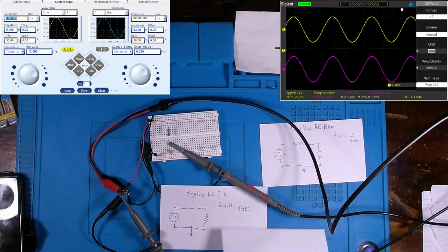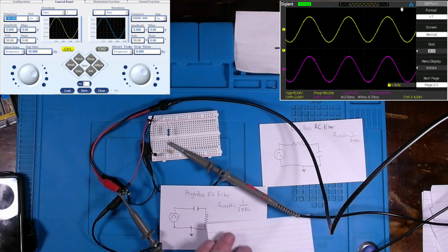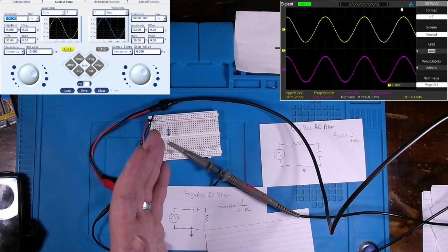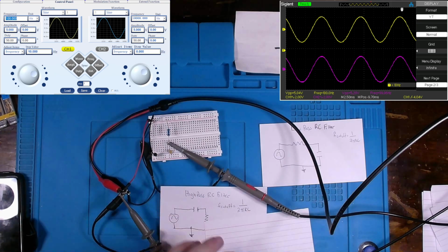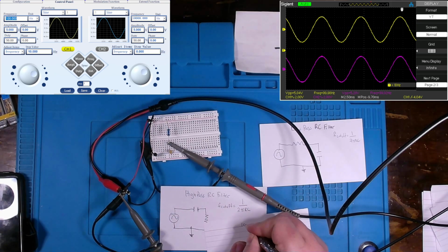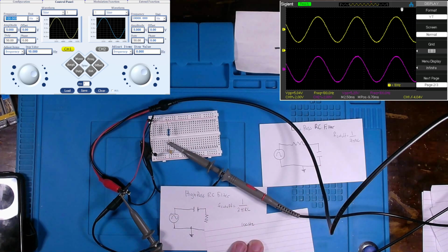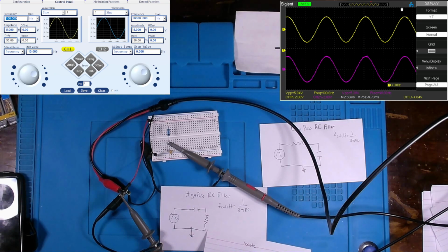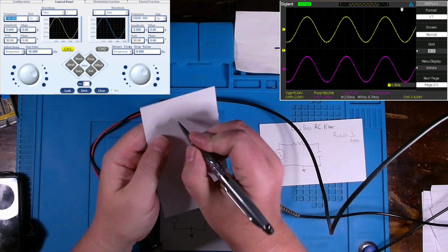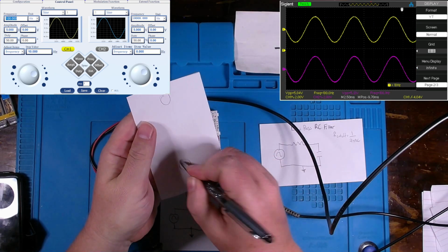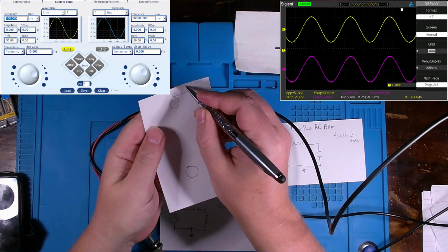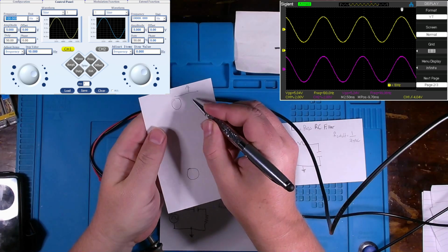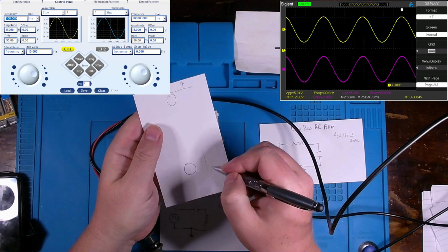I'd like to start that attenuation slightly higher than 60 hertz, so I would say 100 hertz is kind of where my aim is, with things below that attenuated. So when we talked about the low pass filter, everything above this point was attenuated, and everything below that frequency passed through.